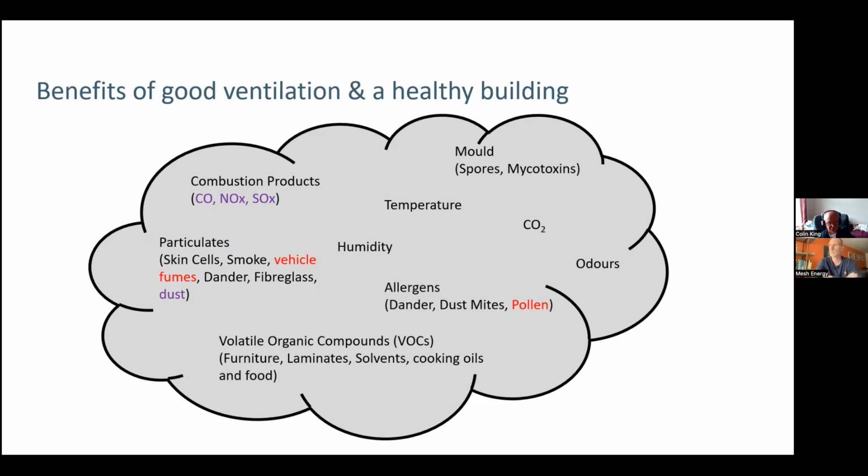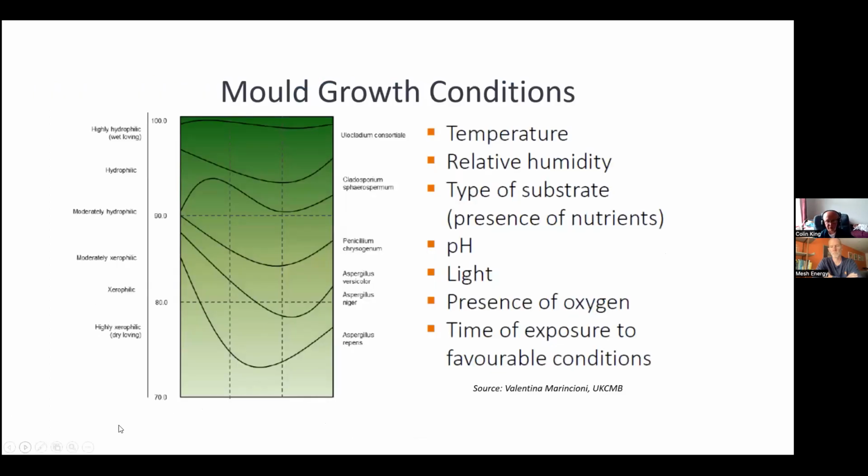You know, I've seen some fairly ridiculous claims by people saying that they've got a system that can indicate when mold's going to grow 7 months before it happens. You know, it's a complete load of toss. Once you get those ideal conditions, mold can grow within 7 hours, 12 hours, and will be visible within a week. And then you've got to worry about, well, what type of mold is it? Because there are lots of different ones.